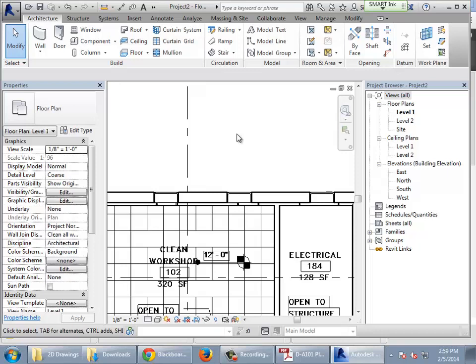becomes even more important, so that whatever walls are used on level 1, level 2 is also using, and level 3 is also using. So even before everyone does a whole lot of modeling, it's really good to spend some time just going through the drawings and trying to figure out how many wall types there are in this building. There are probably 4 or 5 major ones that will get 95% of it. Then everyone has those to work with so that you don't have to recreate them all from scratch. Beauty. Okay, let us do this.